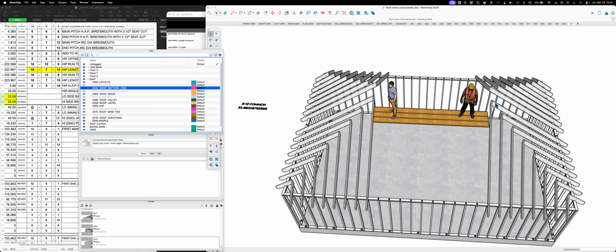You could drive a nail through the back side and hang them all along the wall so that when they get to the point of doing jacks, all they got to do is step down, pull this up, get it snug, shoot the bottom, shoot into the hip, and then drive that nail in also. So let's just put the hips back in there.